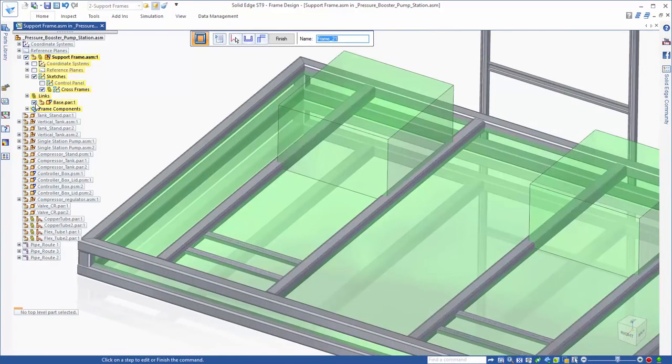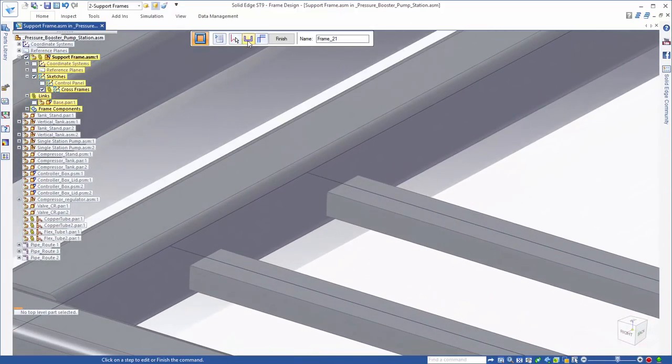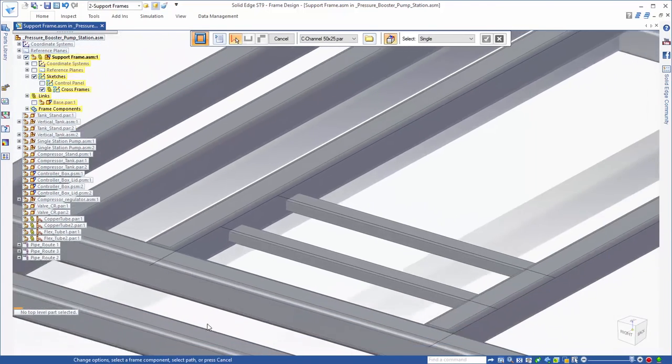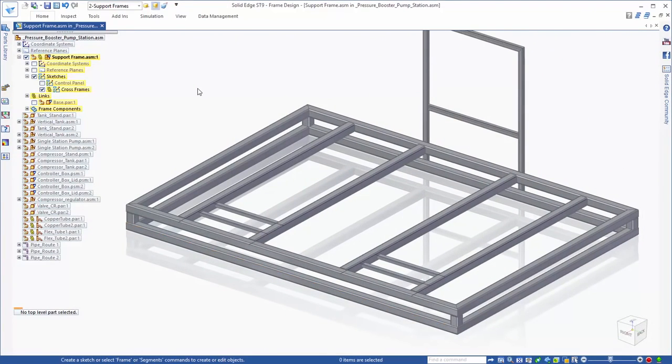Once our pump supports are in place, we need to adjust how the member cross sections align to the larger beams. Solid Edge provides full control of cross-section location, whether aligning to the controlling sketch from the outside edges, middle, or any key point desired. Proper placement is a breeze. Also, notice that we're editing multiple cross-sections simultaneously, eliminating the hassle of editing each individually.